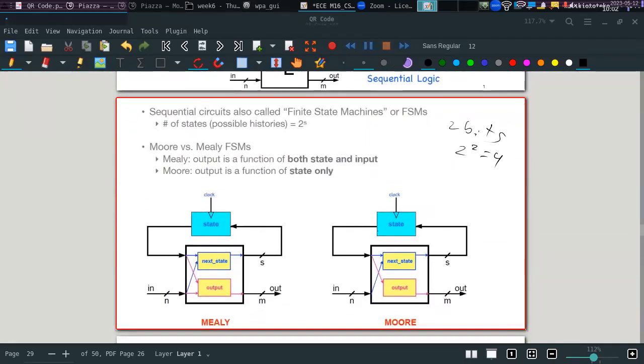The way you actually describe this sequential logic is through finite state machines, which you will see in the lectures, which are something like this. If you represent with diagrams such as this, you first say, if you are in state 0, what are the conditions you need to have in the input to get to state 1? And in state 1, you'll be having as an output something.